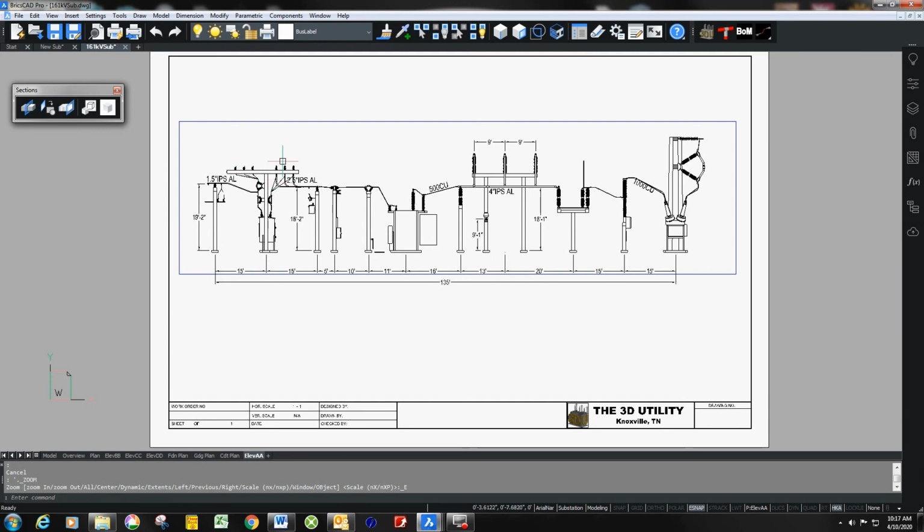It's kind of hard to dimension these buses, but you could put a dimension on one of them and mark it as typical, and they should know then that all of those buses have the same dimension between them. This bus is, for some reason, set off a little bit on this side, so you may need to give a dimension from the center line on both of these so they can see how they sit there. Because if you make them guess, they'll throw a scale on it and come up with their best guess. If that doesn't bother you, then fine. Otherwise, have at it.